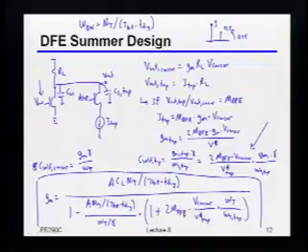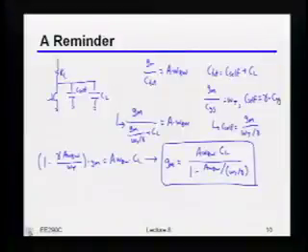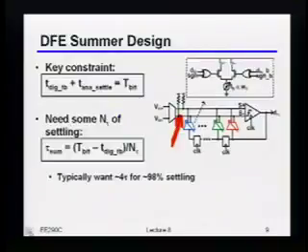Yeah. So if you have more than one tap, which digital delay will you use? Say that again? If you have more than one tap, which digital delay will you use? Okay, so that's a great question, and we'll talk about that in a little bit more detail. So, we'll go back to the picture we had over here. What your question is really getting at is, well, look, there are different digital delays, right? There's one digital delay for that very first tap, and then everything else is a little bit different because that's just straight off of a digital flip-flop.